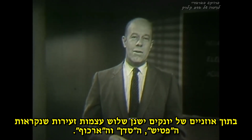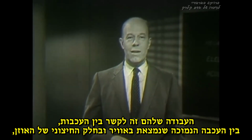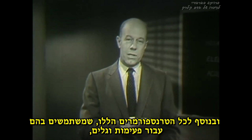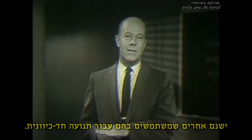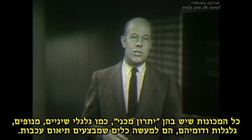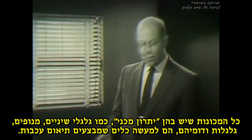Inside the mammalian ear there are three tiny bones called the hammer, the anvil, and the stirrup. Their task is to provide an impedance linkage between the low impedance of the air in the outer ear and the high impedance of the liquid in the inner ear. And in addition to all these transforming devices that are used with pulses and waves, there are others that are employed with unidirectional motion. For example, in mechanics, all of the mechanical advantage machines, such as gear trains and levers and pulleys and the like, are really impedance transforming devices.